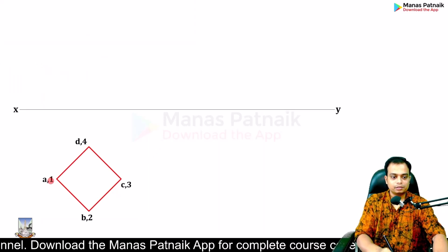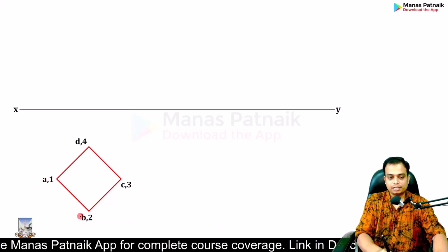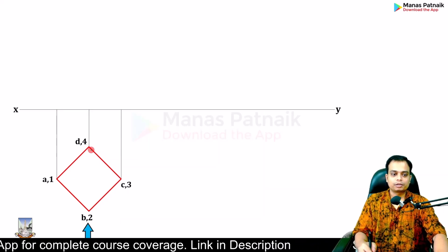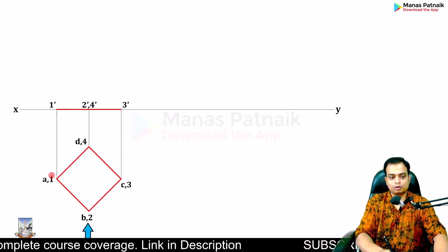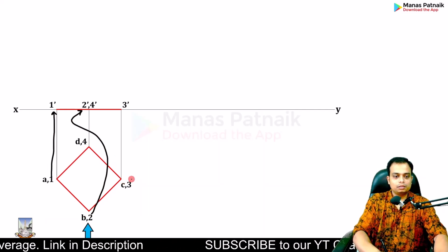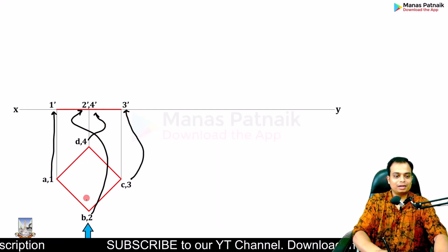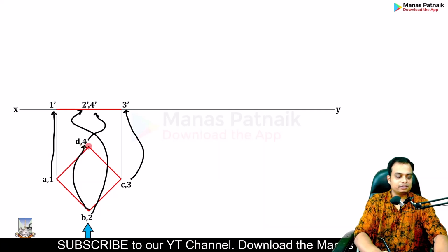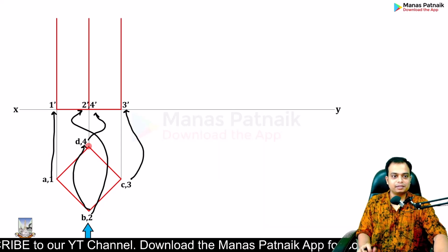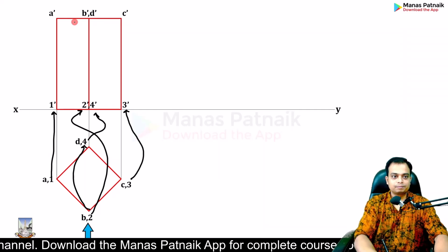This is how you need to do this. Bottom four corners, 1, 2, 3, 4. Top four corners, A, B, C, D. Done. Now let's create the front view. These are the bottom four corners: 1, then you've got 2, then 3, then 4. 4 is just behind 2, as you can see. In the same fashion, you can now give it the height, that is 60 millimeters, and then create the top portion, A, B, C, D.